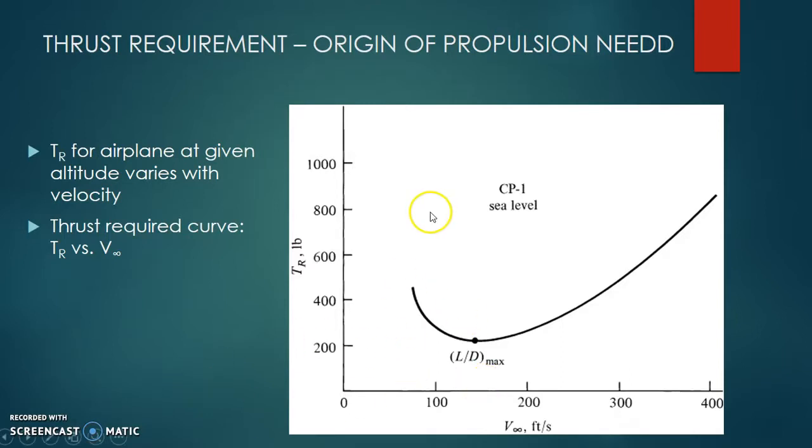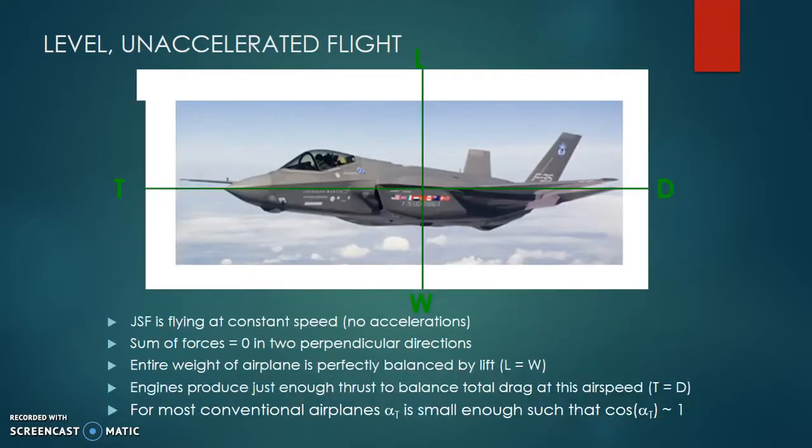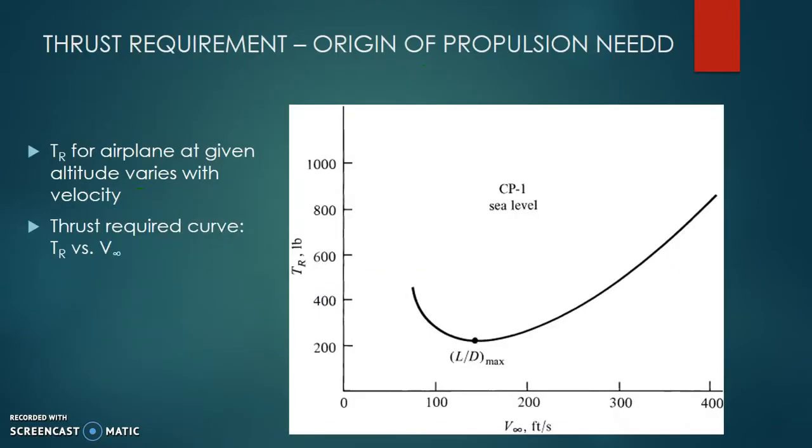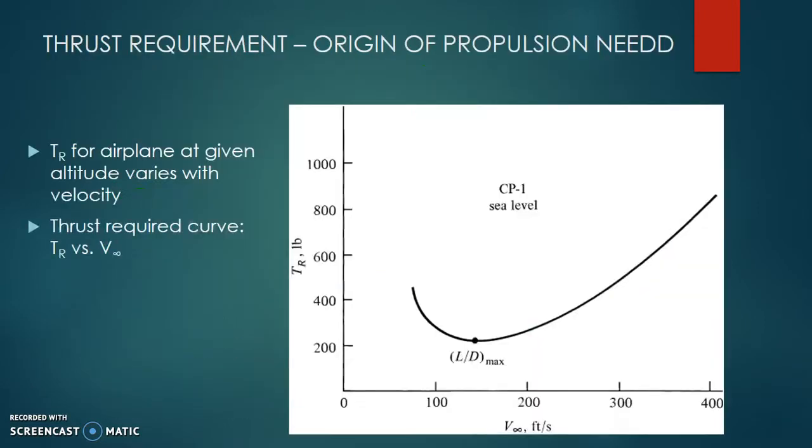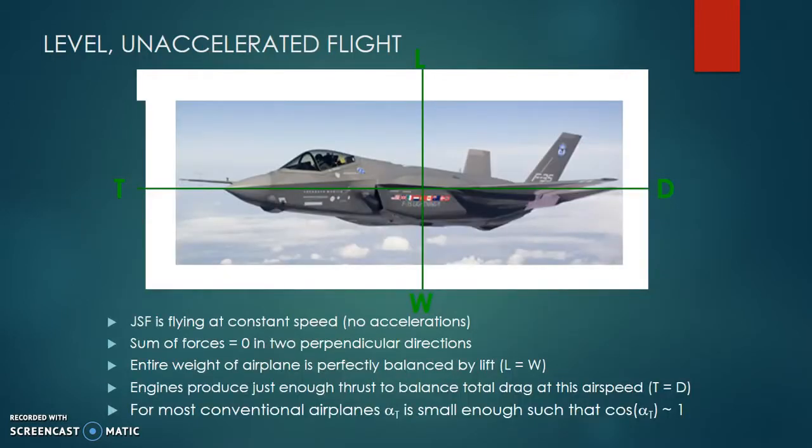As the velocity increases, the thrust actually keeps reducing, which means there is a tendency where the high thrust starts coming down. This is the case because in these particular cases, the drag and the lift are not yet balanced. So you remember these equations. Now, when you are not in cruise mode but in increasing velocity maneuvers, the drag performs as a square function of velocity, and so does the lift.